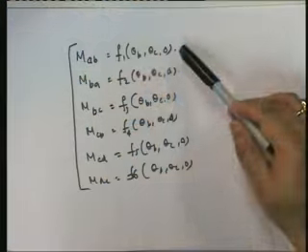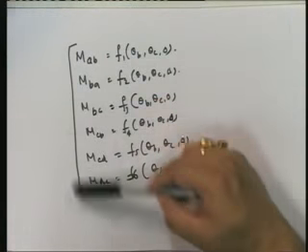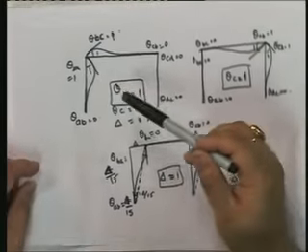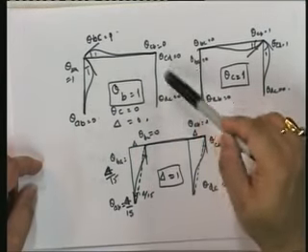I can then write virtual work done by the external loads equal to the virtual work done by the internal loads, and once I put that equal, or the total virtual work is equal to 0, from that I get an equation. Note what will be the equation in terms of? The equation will be in terms of theta b, theta c, because these are the internal forces, and I am going to find out for each displacement pattern what are the